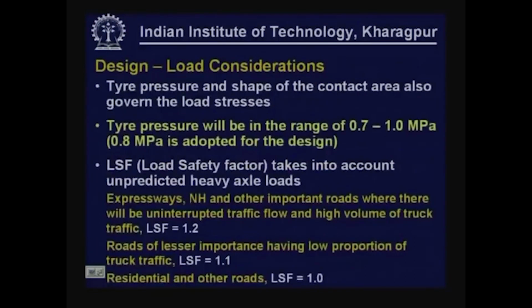Other traffic related or load related considerations are tire pressure and shape of the contact area, which also govern the load stresses. Tire pressure will be in the range of about 0.7 to 1 MPa. So, 0.8 MPa is recommended for consideration in the design. Load safety factor is also used, which takes into account the unpredicted heavy axle loads.